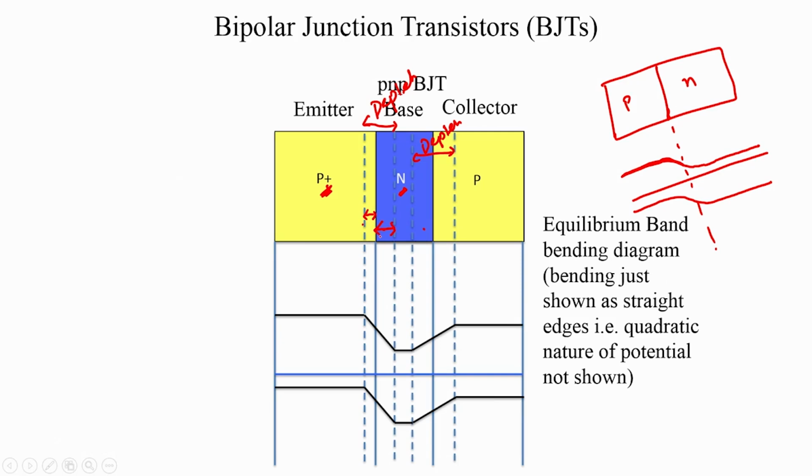And why is that? Because for a PN junction, because of the continuity of the electric field at the junction, we had the condition that XDN times ND equals XDP times NA. This means that as the doping concentration increases, XDP has to come down, and therefore the depletion width here is smaller compared to the depletion width here, because the doping concentration here is larger. I have tried to represent that as accurately as possible.